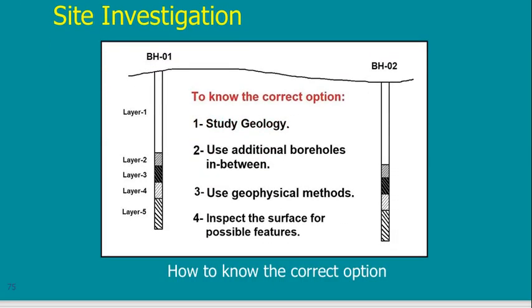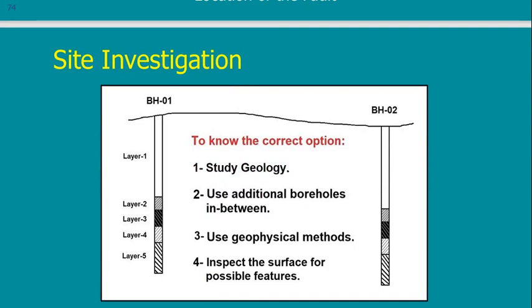So now what should I do in a site investigation? I will have just boreholes. To do a correct site investigation, I should join it with the following points as needed. Study geology. Of course, this should be in any site investigation. If you are doing a site investigation and you don't know about geology, it's a problem. Use additional boreholes in between.